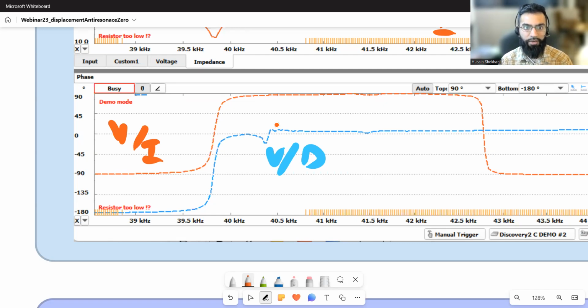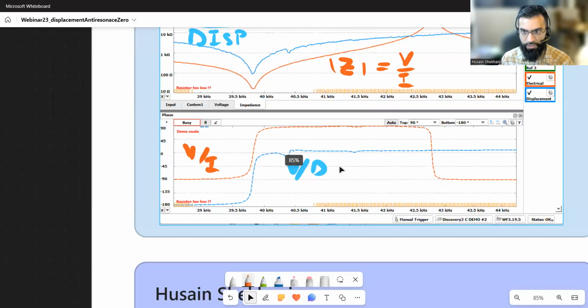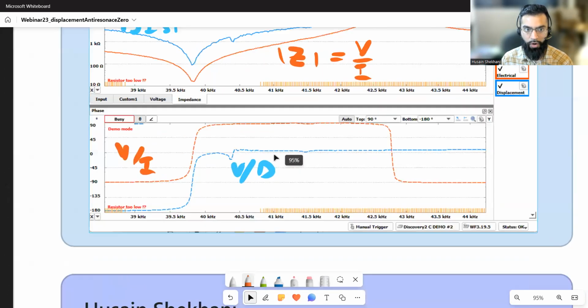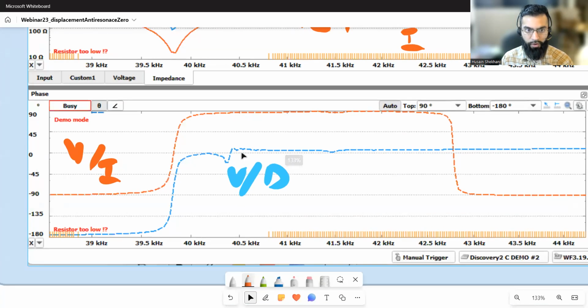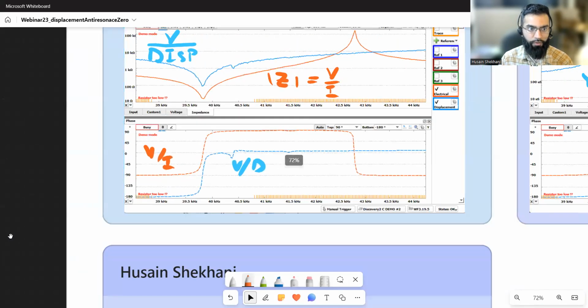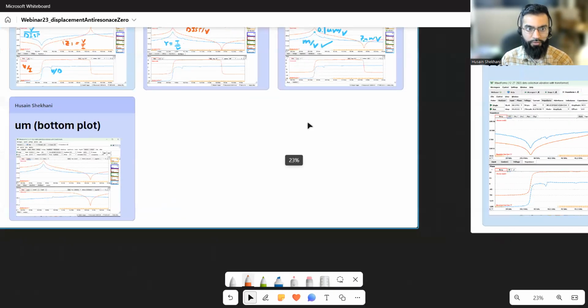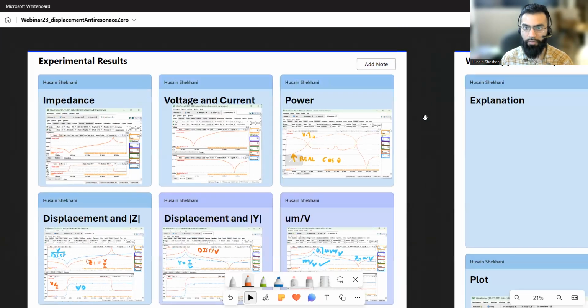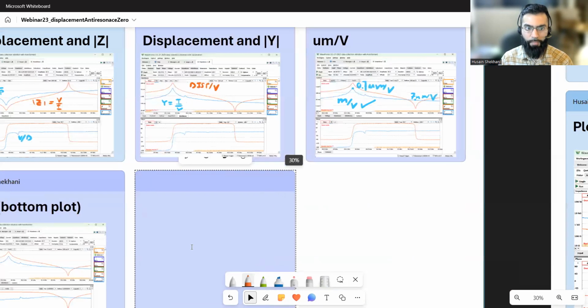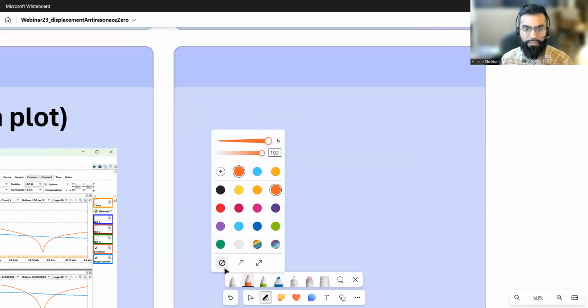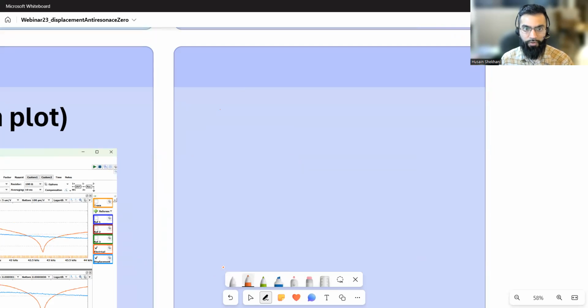But the only thing here is you're going to notice the values that, usually for a vibrometer, and this is important, if you use a vibrometer, you have to correct the phase values for how you are situated and oriented. It's pretty obvious actually if you draw it out. Maybe I'll just draw it out one more time. I'm going to decrease this size here so I can draw.